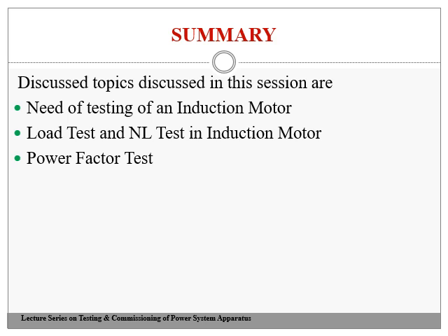Then we came to know about the PI, the polarization index, which is a good tool to indicate the degree of dryness. Depending upon the type or class of insulation you use, the PI should be greater than some values. If it becomes less than that value, then that induction motor should be dried until you get the PI value or insulation resistance to the specified value according to the standards.